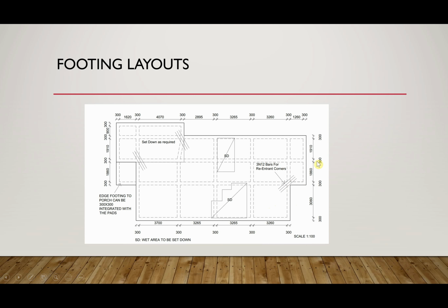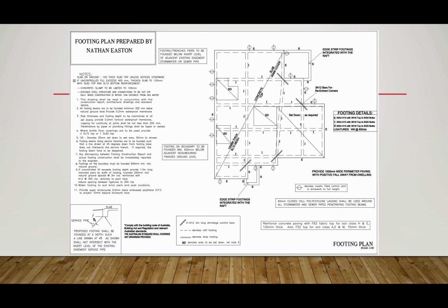Usually we do not put in measurements for our footing layouts. We check them, so we make sure that our centers are less than 4 meters, but we do not put measurements on here. They get them from the floor plan. So here's what a detailed footing layout looks like. These here are for the control joints, which we're going to ignore in our course. You will learn that down in geotechnical engineering, but this is the kind of level that you will need to get to. Okay.